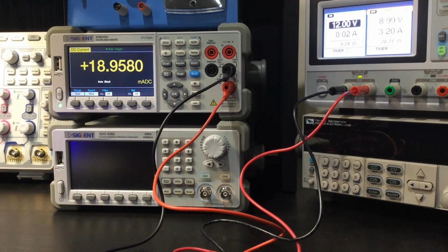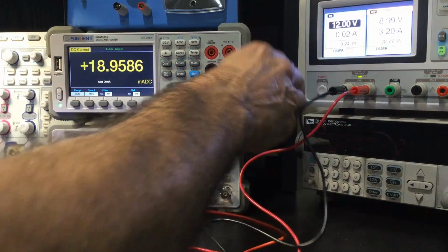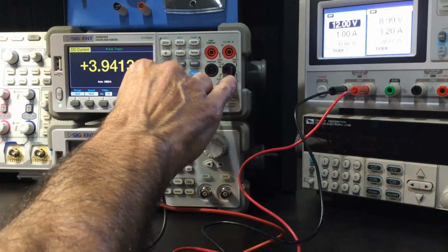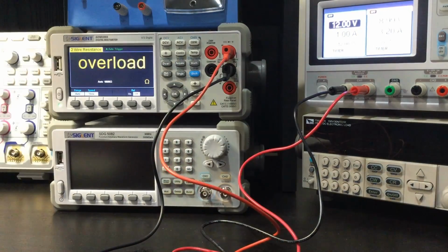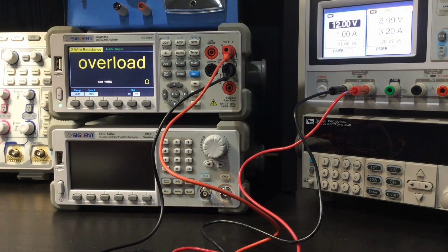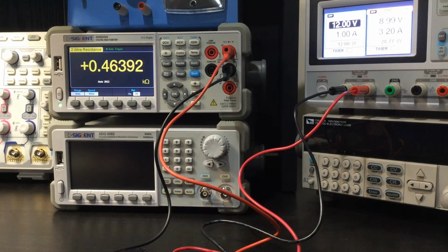Keep in mind, of course, that these are 5% resistors. So we can actually check that. That's something else that we can look at. Let's power the circuit off. Let's switch our meter into 2-wire ohms mode. Go back into the connector here. And let's pull that resistor and measure its actual value. And there we go. So we had said it's a 470 ohm resistor as marked, and it's actually 464. So, 0.464 kiloohms is 464 ohms. So that's certainly within the 5% tolerance of the resistor.